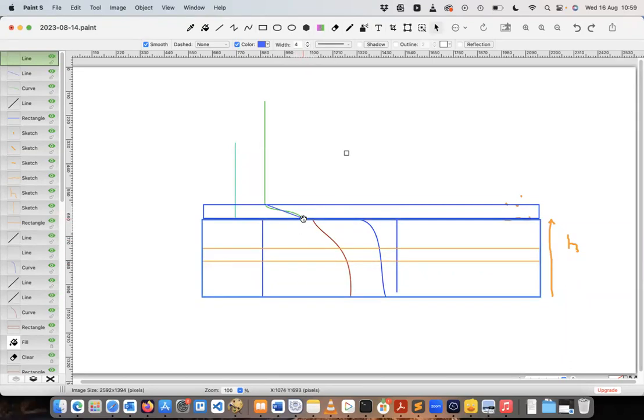But just next to the interface, the flux of water there must equal the flux just above that point. And the reason it must be equal is that there's no space here for any water to accumulate, right? And understand this carefully. Sometimes we say two rates are equal if there's no change in time. Sometimes because of steady state, we say two rates are equal. Here, we are not talking about a steady state.